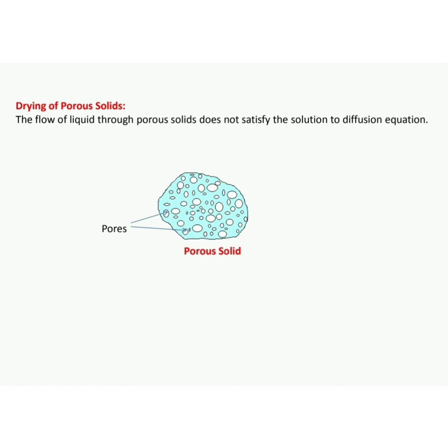Moisture flows through porous solids by capillarity and to some extent by surface diffusion. A porous solid contains a complicated network of pores. At the surface, various sized pores mouths are present. As vaporization starts, meniscus across each pore is formed which sets up a capillary force by interfacial tension between the water and the solid. The capillary forces are in the direction perpendicular to the surface of solid.